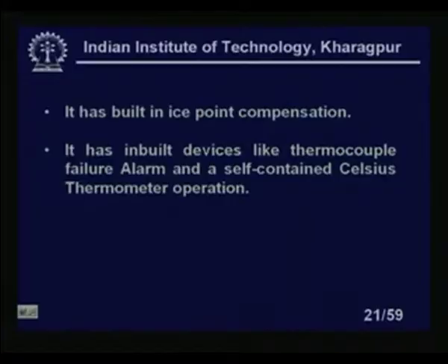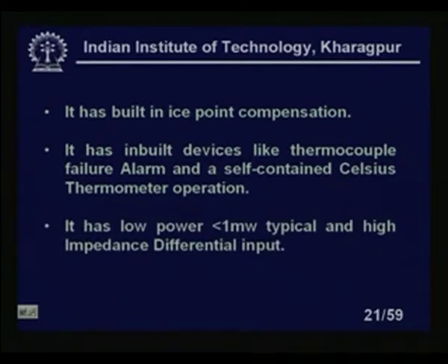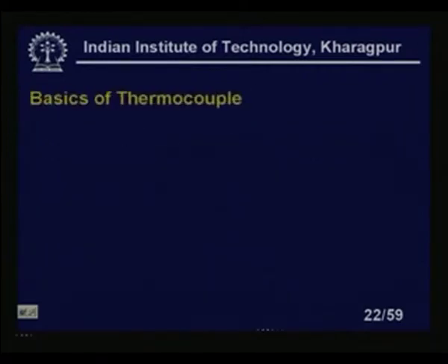And a self-contained Celsius thermometer operation is also possible. Direct readings of the thermometer in temperature degree centigrade is possible. There is another advantage. It has low power, less than 1 milliwatt typically, and a high impedance differential input is there. So the common mode noise problem can be immediately eliminated.